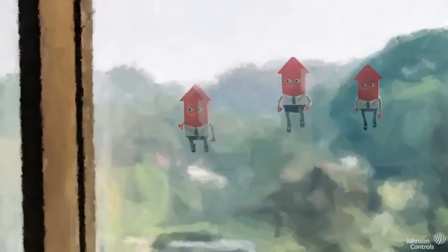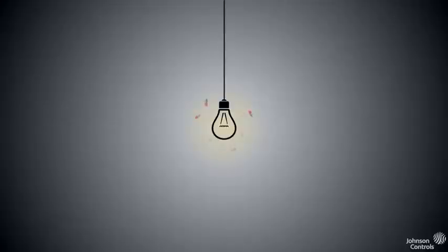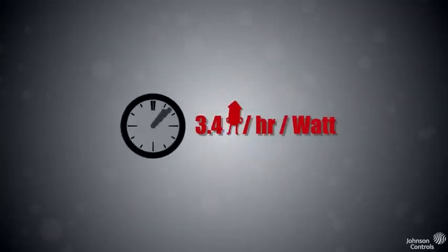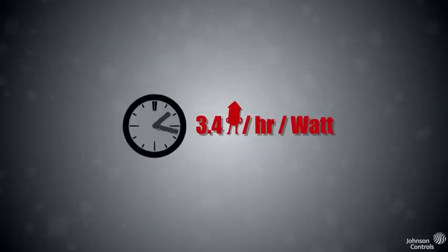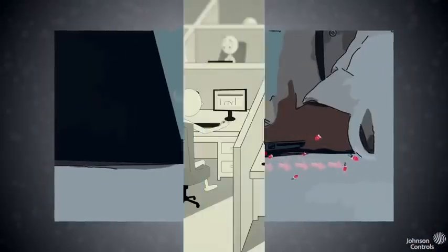Heat from outside on a hot summer day will infiltrate into our space. The sun's energy beaming through windows adds BTUs. Any electrical consumption generates BTUs at a rate of 3.4 BTUs per hour per watt. Notice the heat coming off the lighting fixtures and the computers in the room.